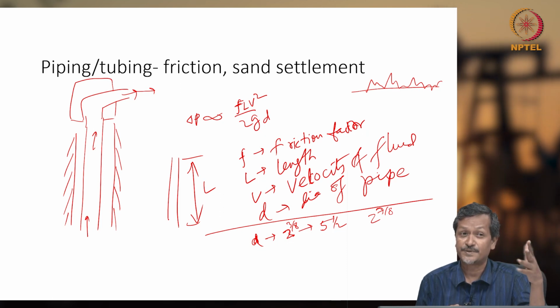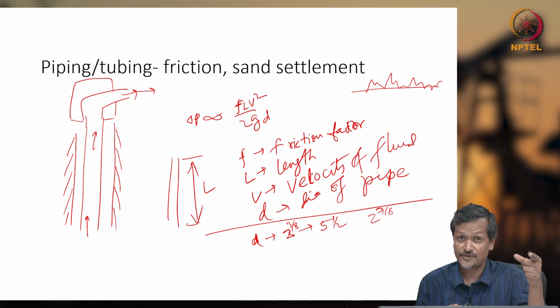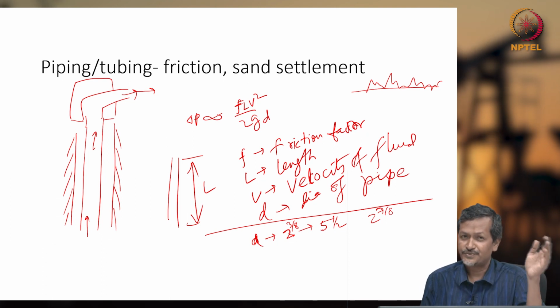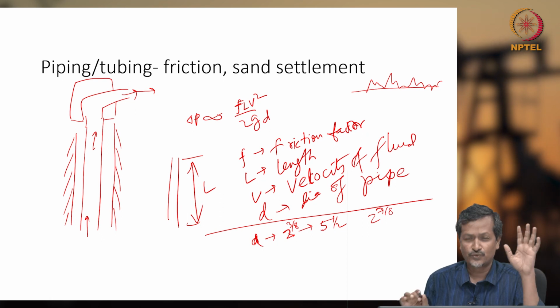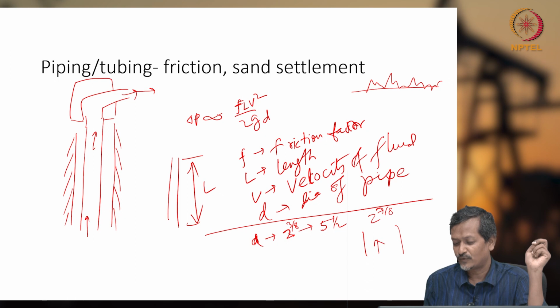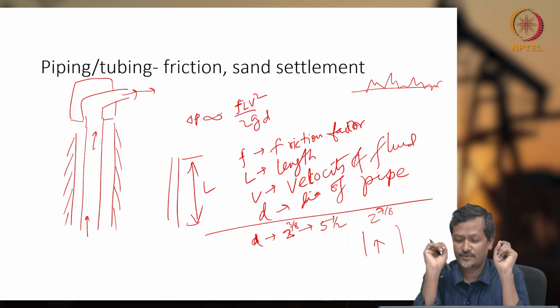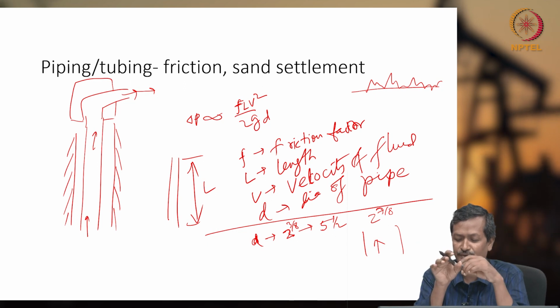Normally they will be specifying the outer diameter. In a diameter you have to calculate when you are calculating for fluid flow inside tubing. Now you change the piping diameter to 5 inch, for example. What will happen? Fluid flow rate will go down because, with the same pressure, the same flow rate you are maintaining, so velocity will go down. Flow rate will be maintained, but velocity going down.